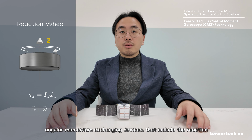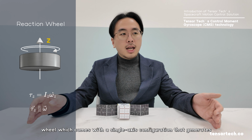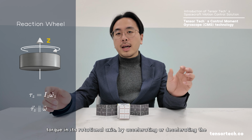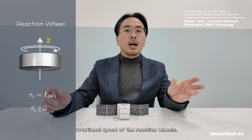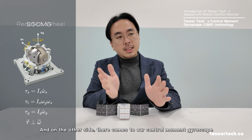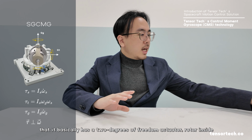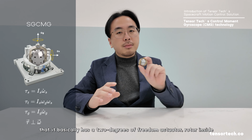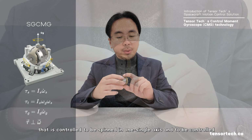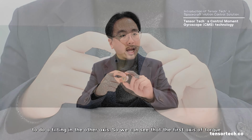That includes the reaction wheels, which come with a single axis configuration that generates torque in its rotational axis by accelerating or decelerating the rotational speed of the reaction wheel. And on the other side, there is our control moment gyroscope, which basically has a 2 degrees of freedom actuator, a rotor inside that is controlled to spin in one single axis and to tilt in the other axis.